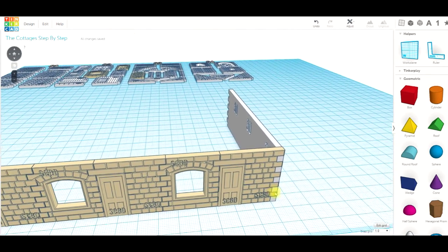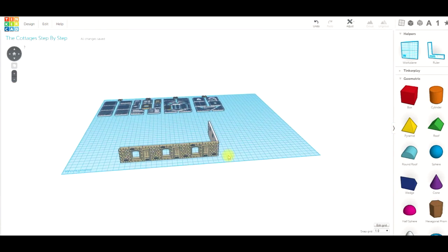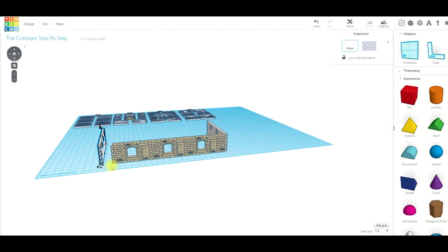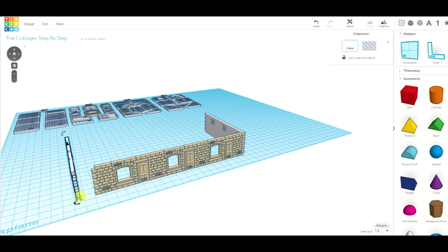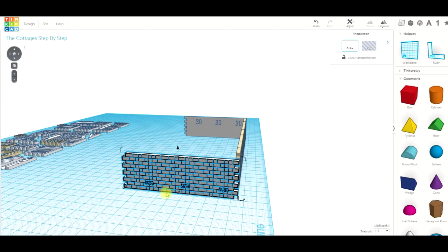So if we were going to do exactly the same on the other side, let's have a look at that. Pick up this set of pieces, Control and Duplicate it, and just slide it with your left arrow key until it's over to the other side, because no need to build that wall again, and spin the whole thing 180 degrees. Okay, now we know that's already on the face line, which is fine. Just by looking along there, we can see they're exactly lined up because all we did is bring it and spin it.